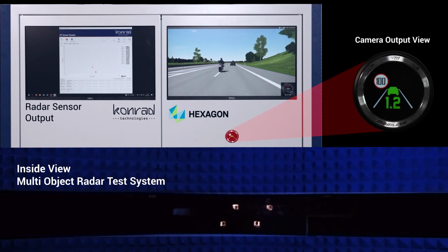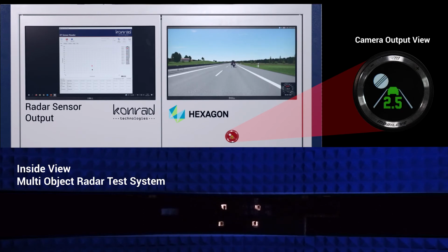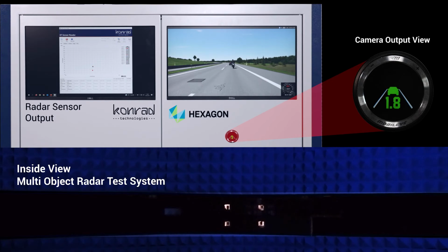For sensor tests, the Mobileye camera correctly implements the forward object identification, lane monitoring, and LDW functions according to the test scenario. The Continental radar sensor output also matches the scenario, validating that both sensors and the ACC module are performing as expected.